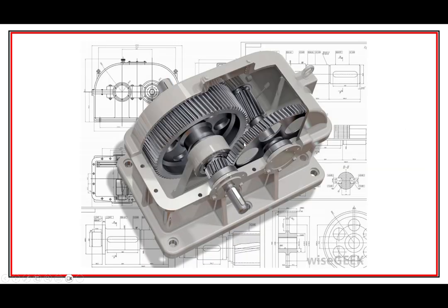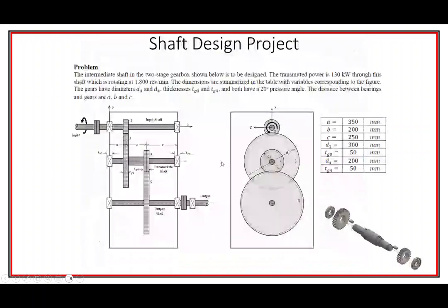Here's another rendering of a gearbox, and this is also two-stage. You just can't quite see. So we have come through here. There's a bearing right here. So this shaft and this shaft are not connected to each other. So there are actually two bearings right in there. The end of this shaft comes into there, and these are helical gears, notably. And so we're transmitting from little gear to big gear through this intermediate shaft. Here's a little gear to big gear, and then the output right there.